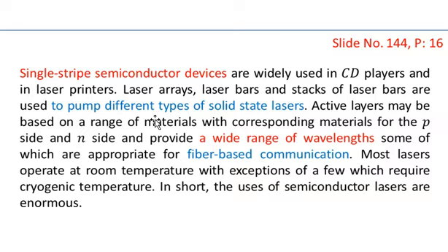Active layers may be based on a range of materials with corresponding materials for the P side and N side, and provide a wide range of wavelengths, some of which are appropriate for fiber-based communication. Most lasers operate at room temperature, with the exception of a few which require cryogenic, that is lower, temperature. In short, uses of semiconductor lasers are enormous.